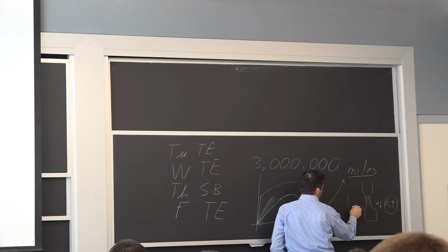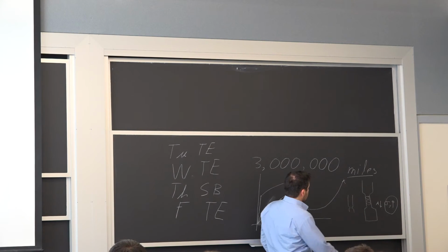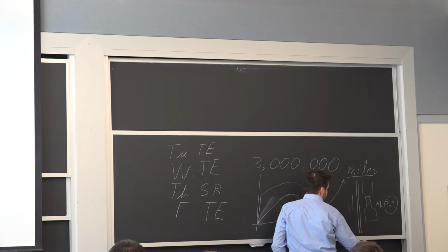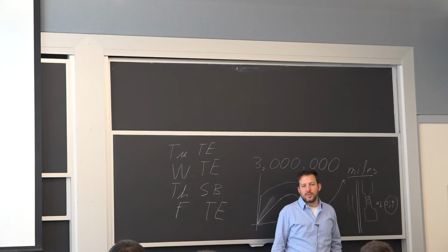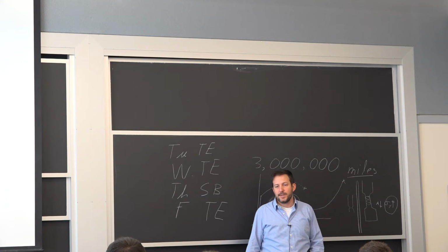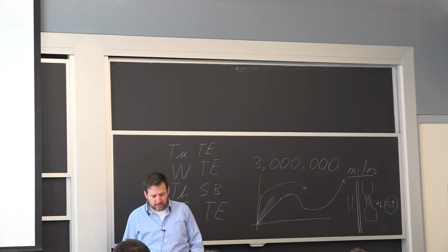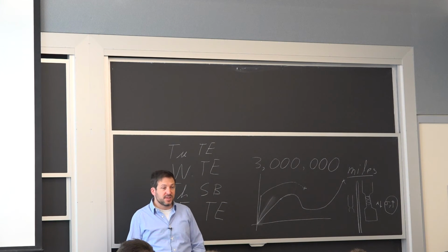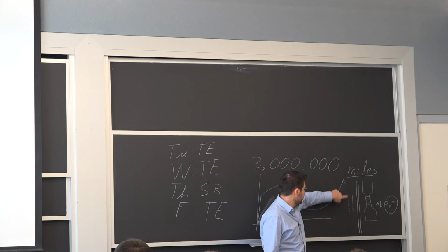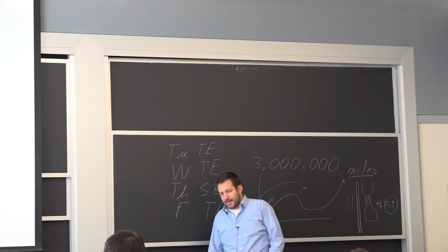Very, very localized. This could be half this thickness. And then the next step is a very, very long, tiny specimen. So that neck is growing in the two directions. So when you see a stress strain curve for a polymer, sometimes it'll go to 600% strain before it breaks here, because you form the neck and then the neck just spreads over the entire length.